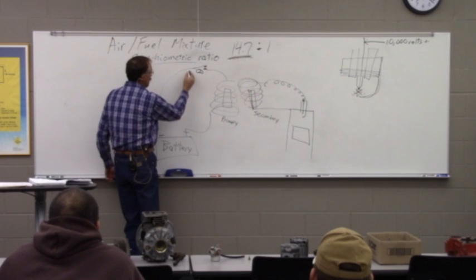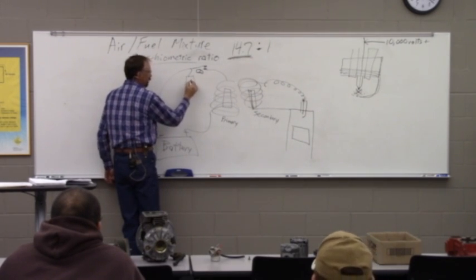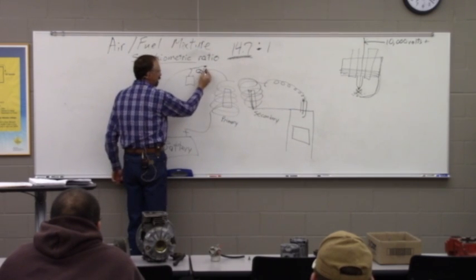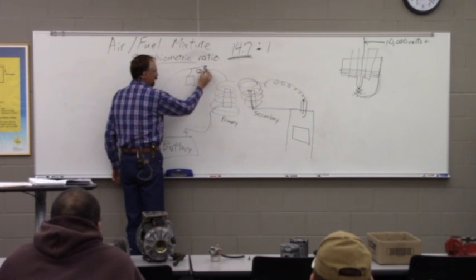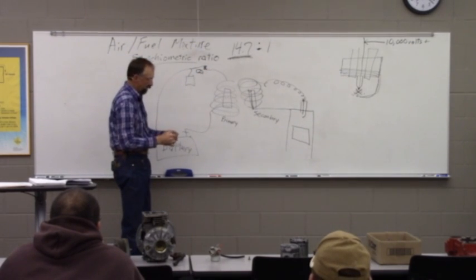Well, the condenser, what it did, it was a little can over here that was made to absorb that pulse that was trying to jump here. And if your condenser was in good shape, it would absorb more of that, and you'd have less of this arcing and burning here, and your points would last longer.